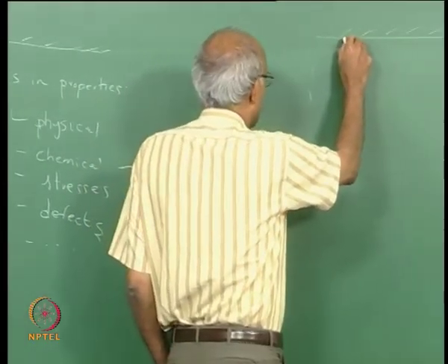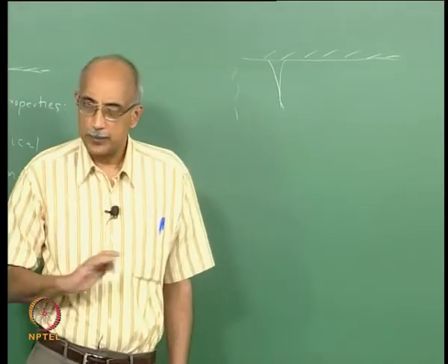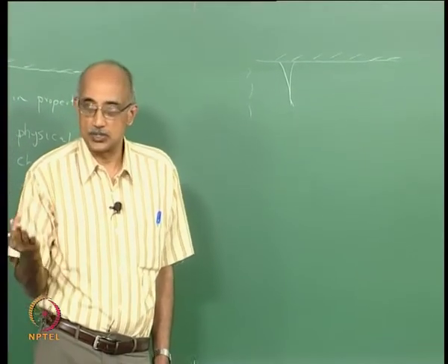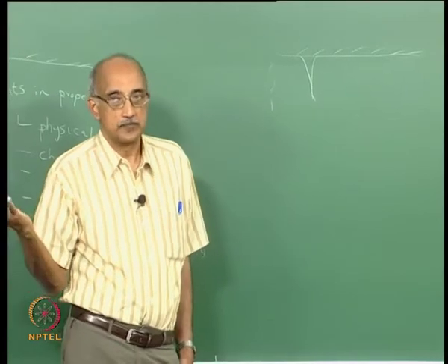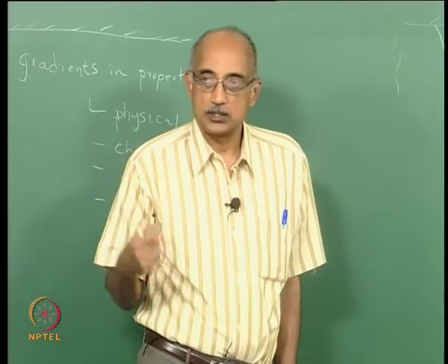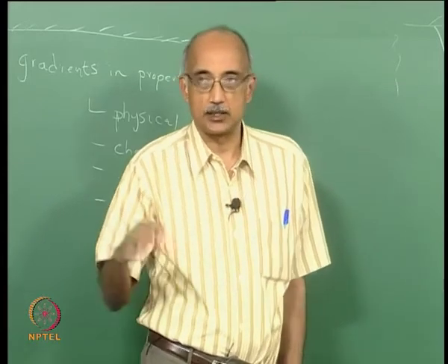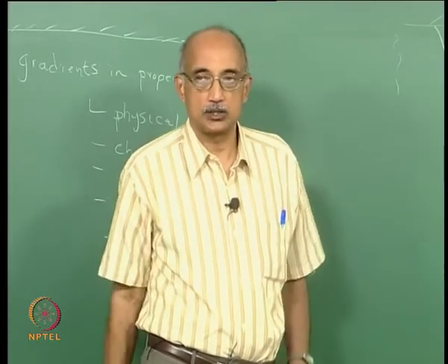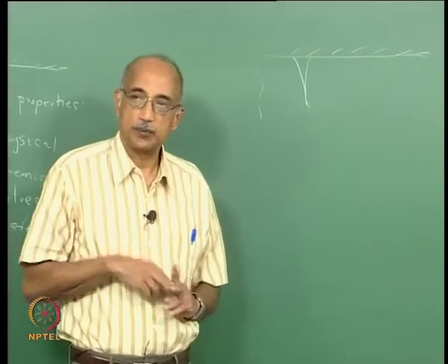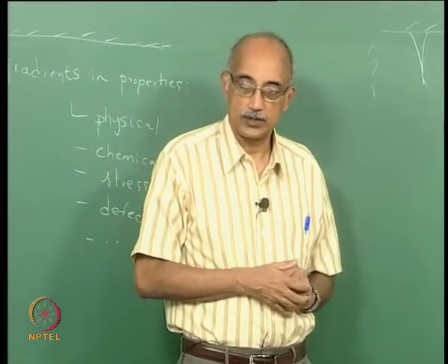The way that in particular liquids get through is slightly different. Vapors, as I said, can penetrate no matter what you do, unless you have a single crystal which has absolutely no openings of any kind, but most materials are not like that. They are either metals or alloys or composite materials where there are sufficient openings, basically in the way the material is put together, to allow for diffusion of species. But liquids will not be able to penetrate into a solid surface or another liquid surface that easily.